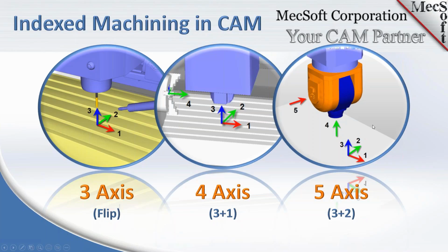And then over here on the right, you'll see your 3-axis orientations as you do in the 3 and the 4, but you also have 2 additional axes for the 5-axis machine, axes 4 and 5. Those are locked in place at any particular orientation that you're machining, and then you're machining the 2 or 3-axis operations in that locked orientation.